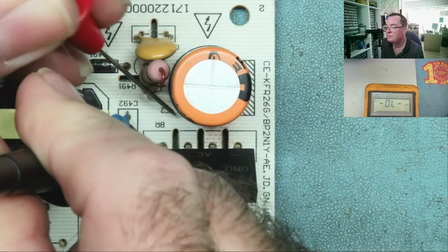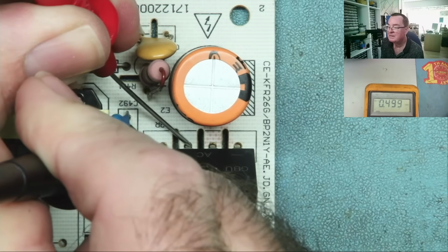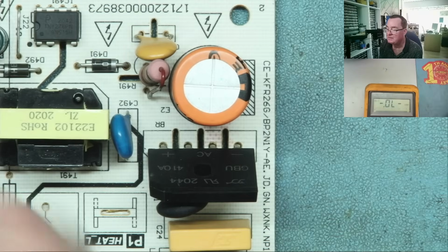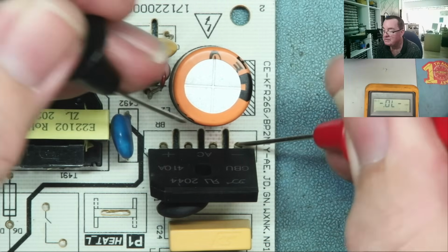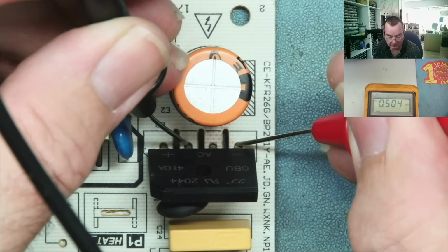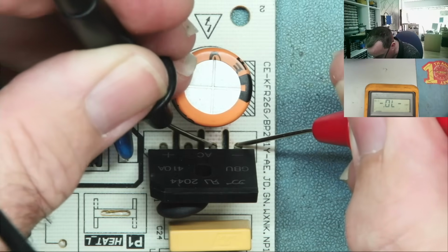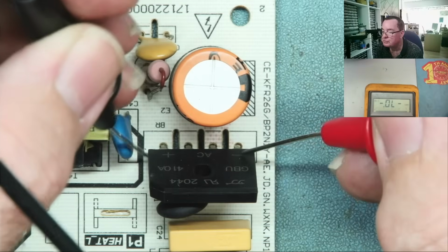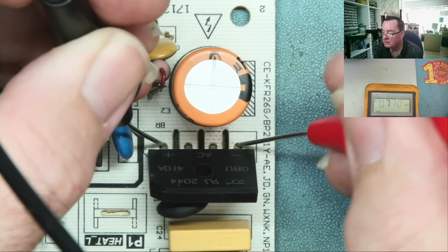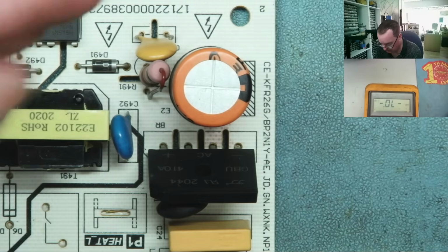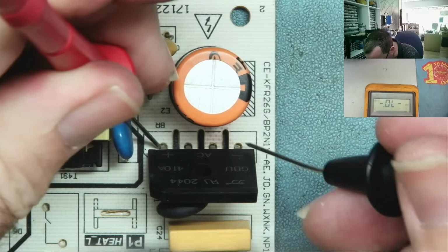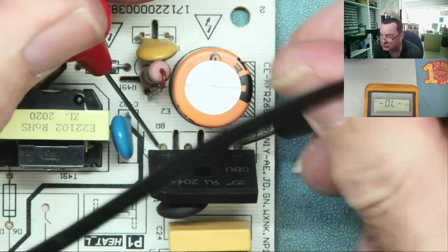Odd to get a connection with the fingers not in the way. And again from that one, and then if we go from the negative with the red lead over here on the negative and put the black diode, we should not see a short across the bridge rectifier. Okay, that reads like a diode this way. Well, that was in the reverse direction, of course.